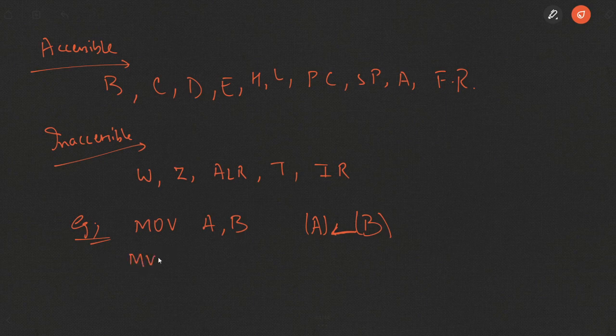Similarly, you can have the instruction MVI C, 50. All the numbers we write in instructions are in hexadecimal. This instruction means move immediately the data given to us to the register C. Or you can have an instruction like ADD D.